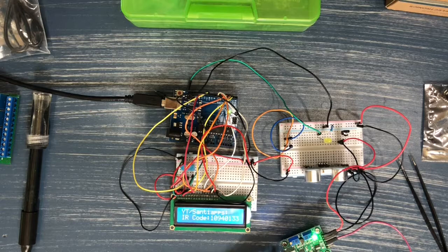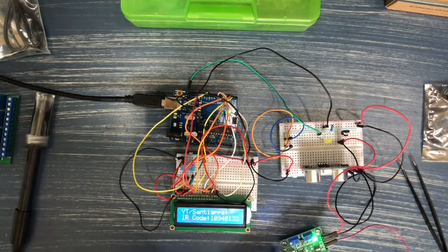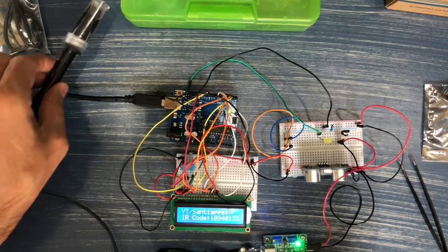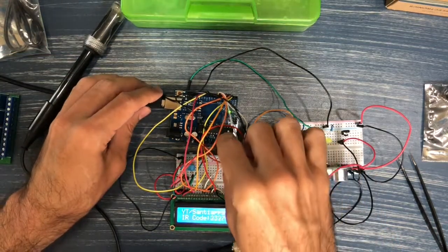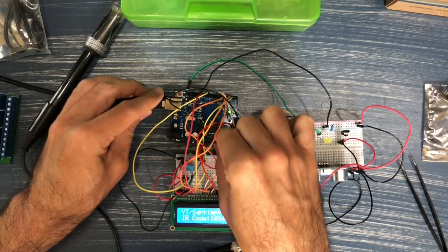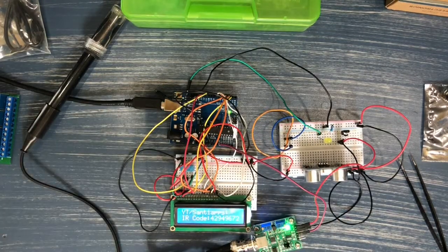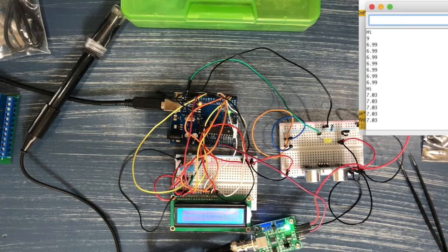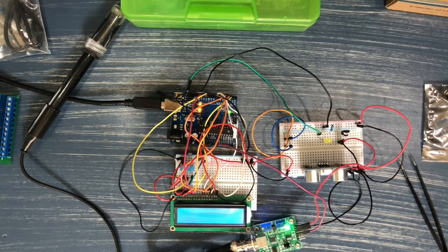And now we need a cable for the actual data pin. And we're going to plug this into A0, which, if you recall, is analog 0. There it is. And okay, so we're ready to upload the code and test this. Wait for it to upload and then open up the serial monitor. And we can see 6.9 pretty consistently. That's supposed to be a neutral solution at 7.0, so 6.9 is pretty close.